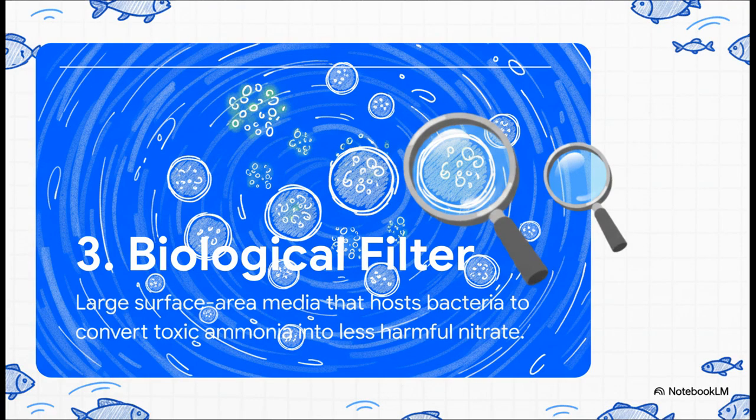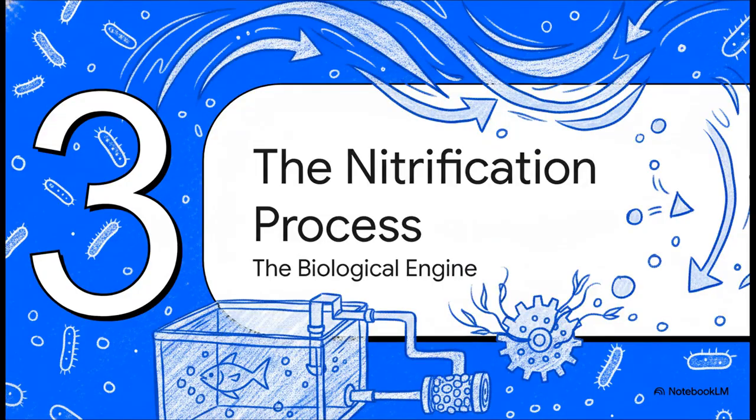Okay, with the big stuff out of the way, our water drop now moves to what I like to call the biological heart of the entire system, the biofilter. This thing is packed with special media, like little plastic bits called bioballs, that have an enormous amount of surface area. But this surface area isn't for physical filtering, it's prime real estate for billions and billions of beneficial bacteria to live on. This bacterial process is so unbelievably important, it's the engine that makes the whole system run. So we need to pause our water's journey for a second and zoom in on it. It's called nitrification, and without it, reusing water on this scale would be impossible.